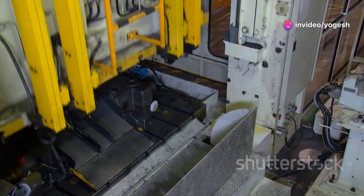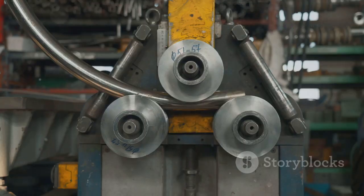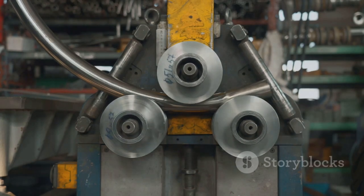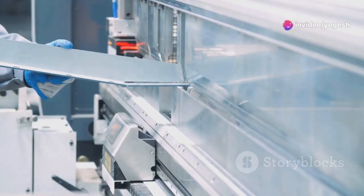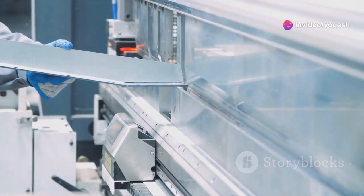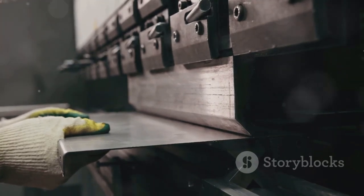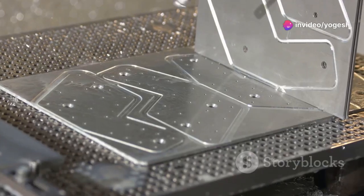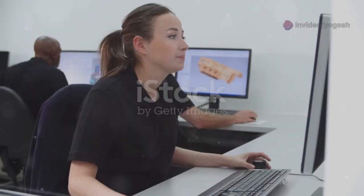Simplify your bends. Fewer bends mean lower cost and faster production. Keep bends in the same direction and on the same line when possible for efficient setups. Use standard bend angles, 90 degree, 45 degree, 30 degree, to match common tooling. Consistent bend radii allow for single machine setups. Avoid unnecessary complexity. Simplicity leads to better, cheaper parts. Uniform thickness and simple bends are the foundation of good sheet metal design.